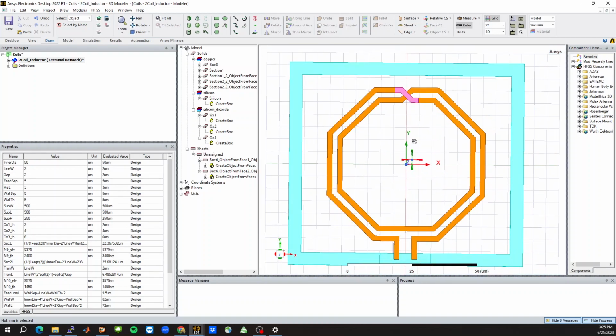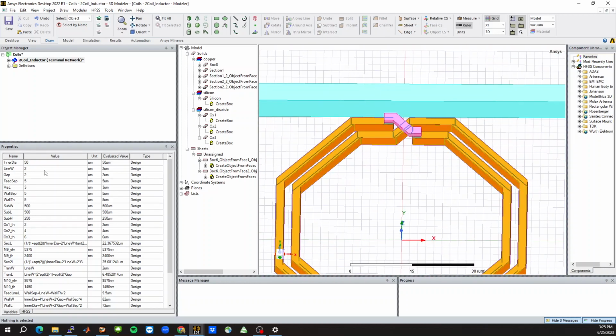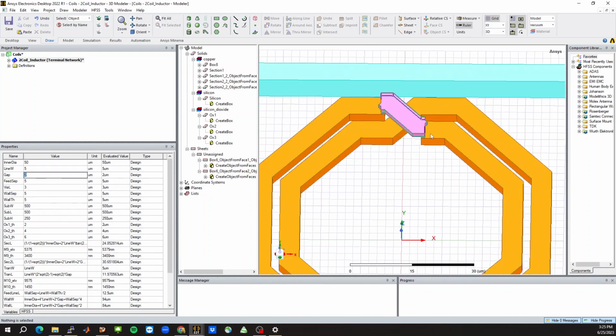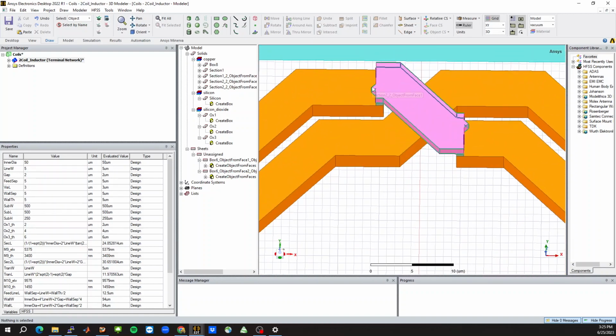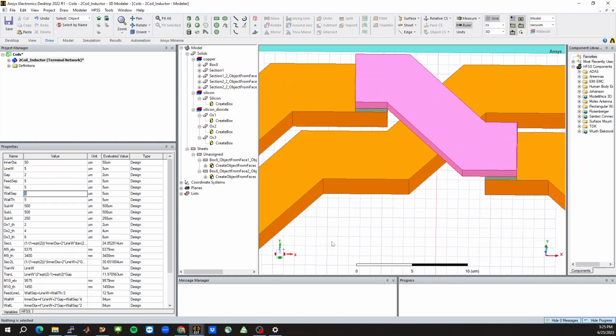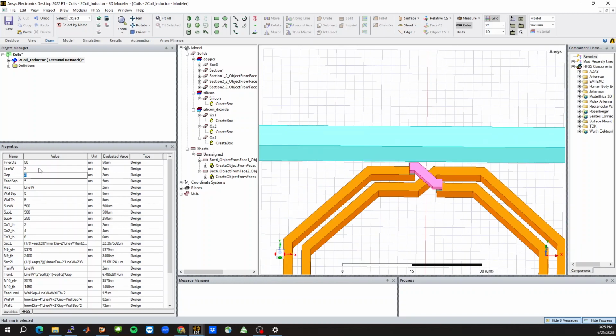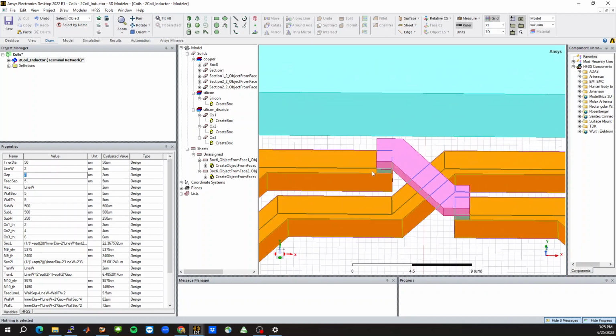It can be a little bit tricky to get the via depth, like the via length, to be correct. So for example, let's say I make the line width 5. So you see it starts showing some bugs here. So you need to make sure this length is also large. One simple way is to just make it the same as the line width. Right, so then even if I make this small, now it may be too small, but it's okay, I think.